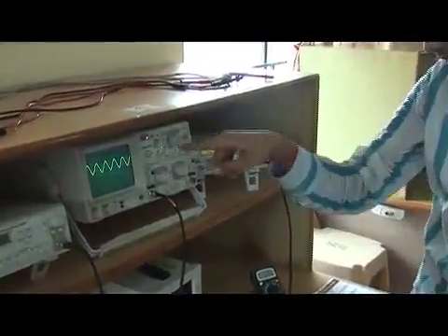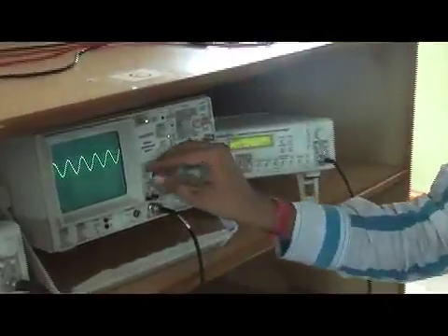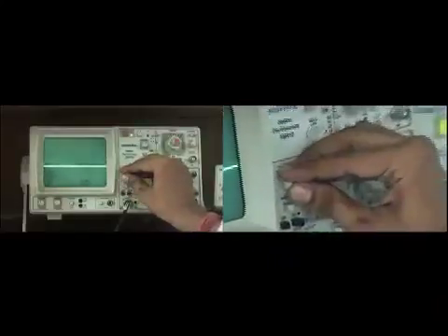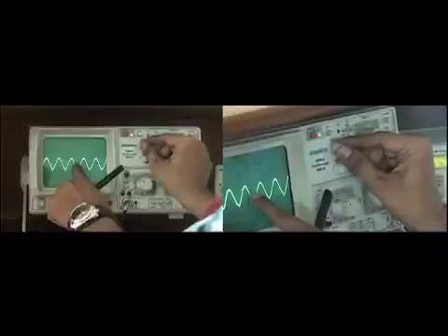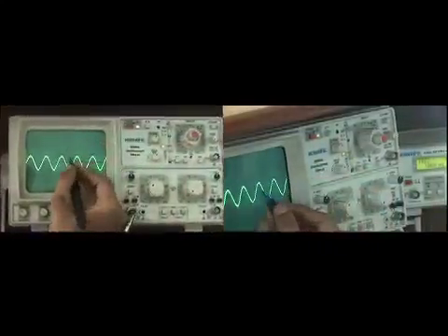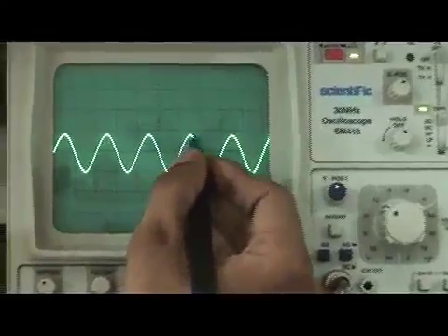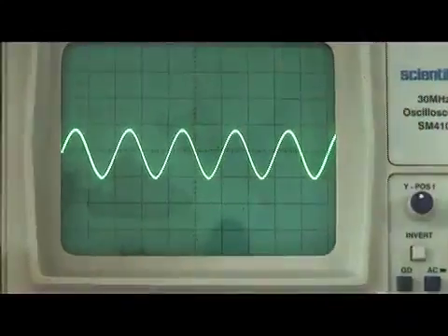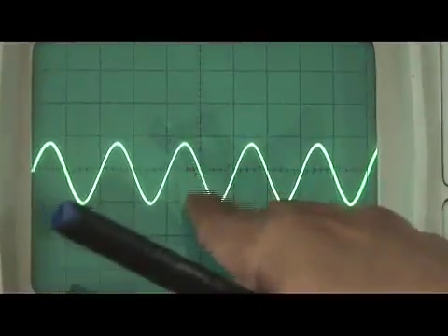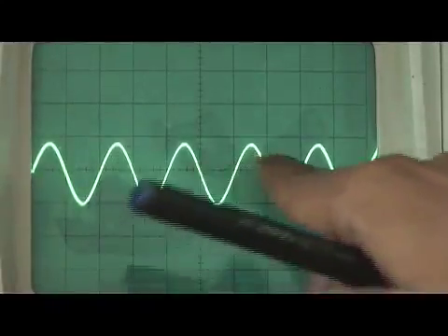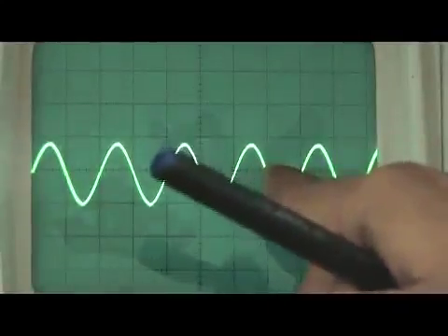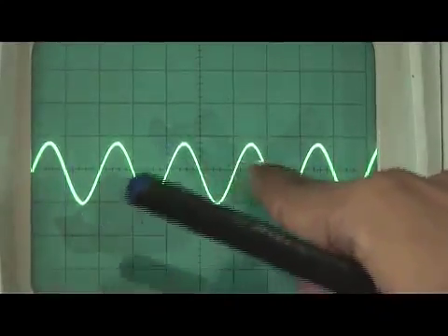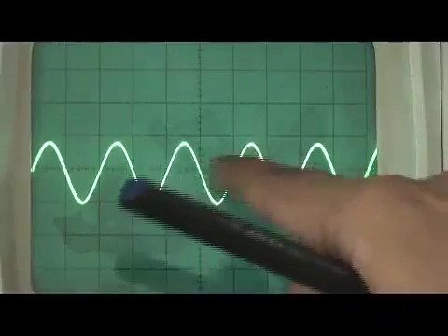Next we move to how to calculate the frequency. Again, make it ground, bring it to the center of the line, release the ground, and set this y-axis in such a way that you can easily count one cycle. If I set it here, from this point to here is my one complete cycle. How many blocks does it require? It requires 1, almost 2, or let us take it as 2. So it is 1 block, 2 blocks. To complete one cycle it requires 2 blocks.